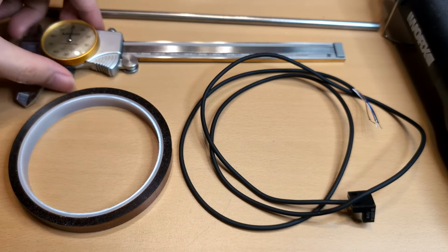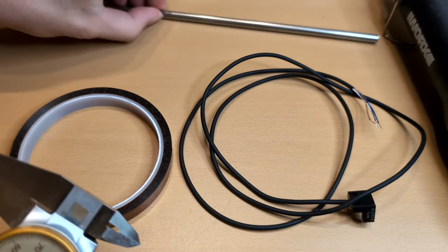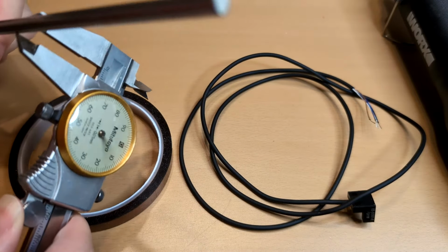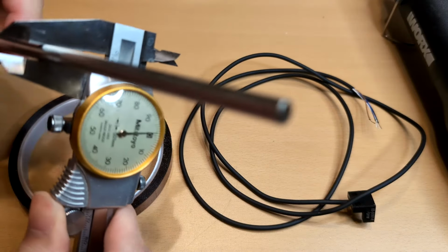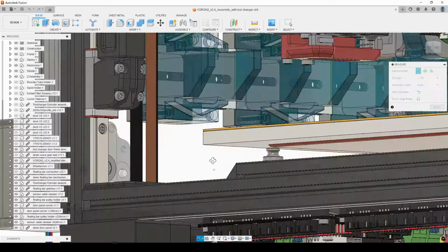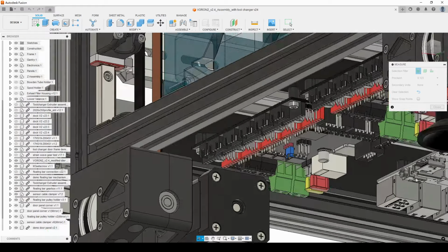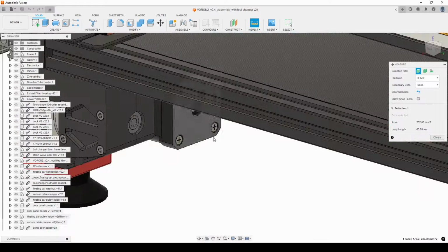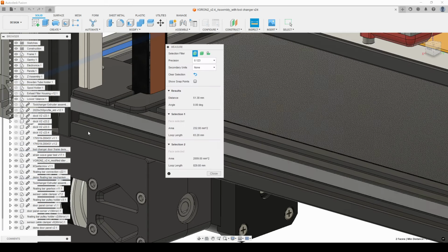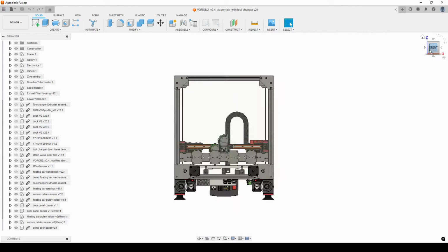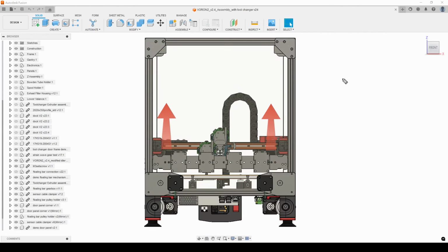Once the bar has been chosen, it's time to calculate its length to determine how much the coiled cable can compensate for the entire movement path of the floating bar. The lowest position of the floating bar is 51.38 mm from the bottom, which is the maximum length for the coiled cable in the shrinkage stage. The total moving length of the floating bar is 368.62 mm.